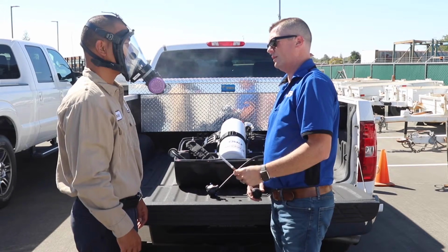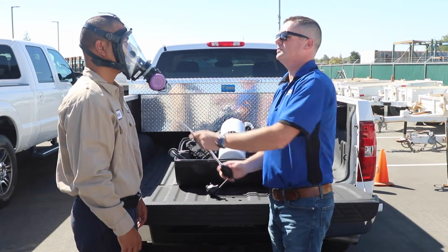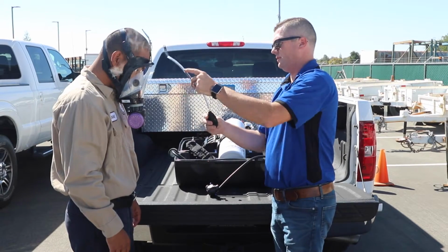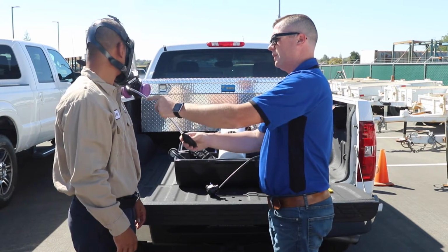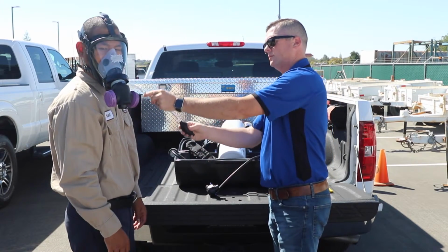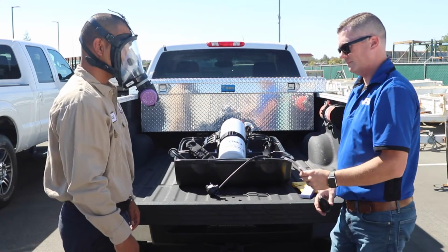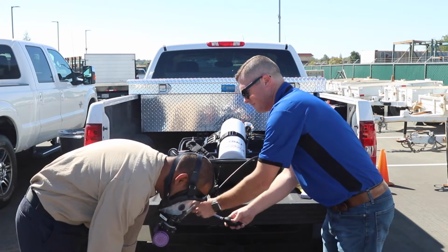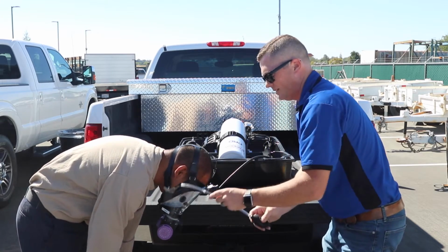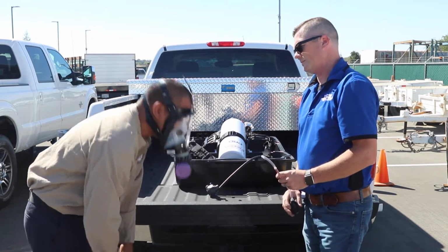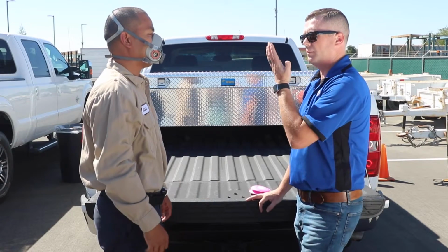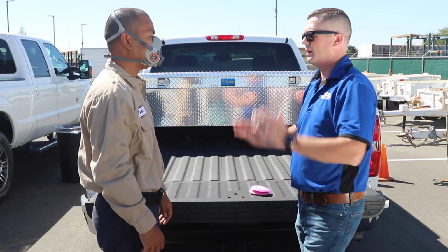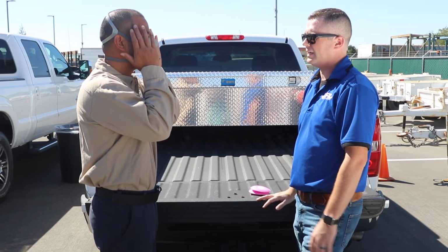Any tight-fitting respirator cannot be worn if you have facial hair or any condition that interferes with the face-to-face piece seal or valve function. Corrective glasses or any other PPE must be worn in a manner that does not interfere with that seal. The seal is so important that even after the fit test, whenever you use the respirator, you must perform a seal check. To perform a seal check, follow the instructions from the manufacturer's recommendations and any instruction you may have received from the person conducting the fit test.